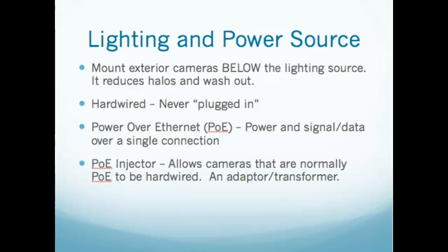Now, many of the modern cameras, and most of them, run on power over Ethernet, which is essentially you're plugging it into an Ethernet port, which is a network port that communicates to the internet, and the minimal amount of power that goes through there is enough to power the camera. So you're getting your camera data going back to your NVR, usually in this case, and your power over that same piece of wire.